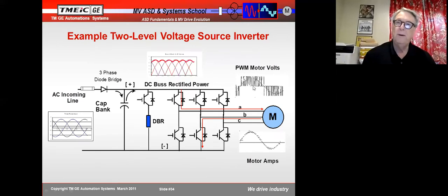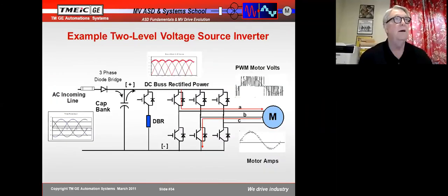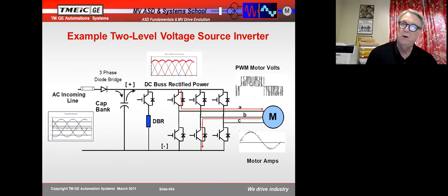So you're basically going from 0 to the peak very, very quickly. And that's what causes a lot of high voltages and breakdown of insulation in low voltage motors. So you know that in a low voltage motor, we like to have a VFD rated motor, and that means it has premium insulation in it, rated about 1600 volts as opposed to 1000 volts. And that's because of these peak voltages. They can cause transient voltages double that size, and so you get some very high voltages in there, and it's hard on motor insulation.